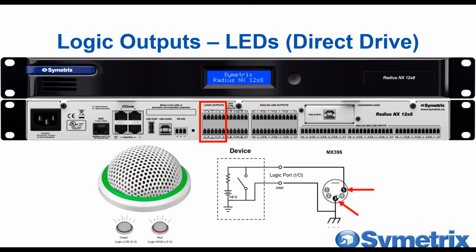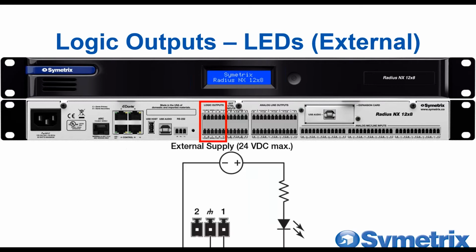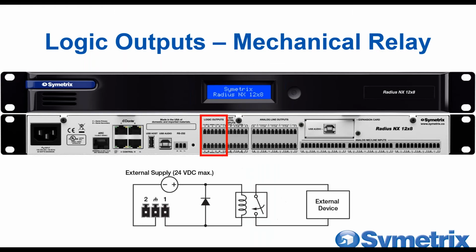If you have a beefier LED, another option is to use an external power supply. So you'd hook that up as below. As long as that power supply, again, is a max of 24 volts, and you don't try to sink more than 50 milliamps into the logic output, this will totally be cool. That's it on LEDs.